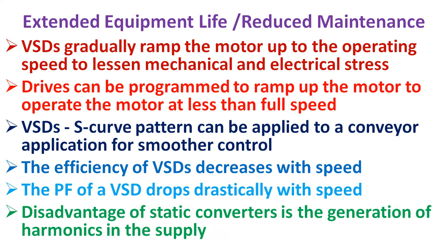In a suitable operating environment, frequency controllers are relatively reliable and need little maintenance. A disadvantage of static converters is the generation of harmonics in the supply, which reduces motor efficiency and reduces motor output. In some cases, it may necessitate using a motor with a higher rating.